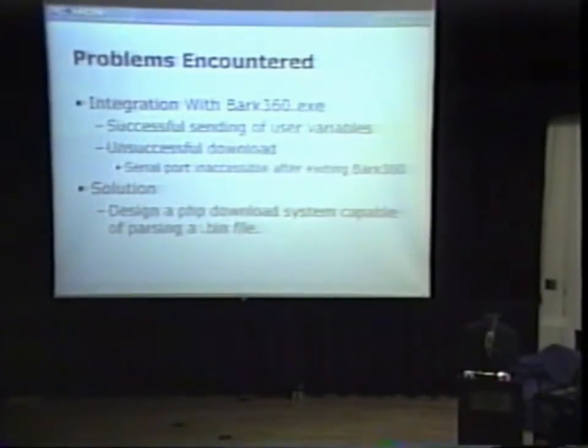Some of my problems encountered. I was going to originally link to bark360.exe, which was a C++ program, which would have saved a lot of time in not having to create my own download system. Unfortunately, bark360.exe did not correctly close the port upon exit, so my software was unable to access the serial port. So I then had to integrate my own software download system into the interface, which posed the problem of parsing through the bin file to actually extract the instructions. The solution was to create the design in PHP that actually parsed through the bin file and successfully put it to RAM.